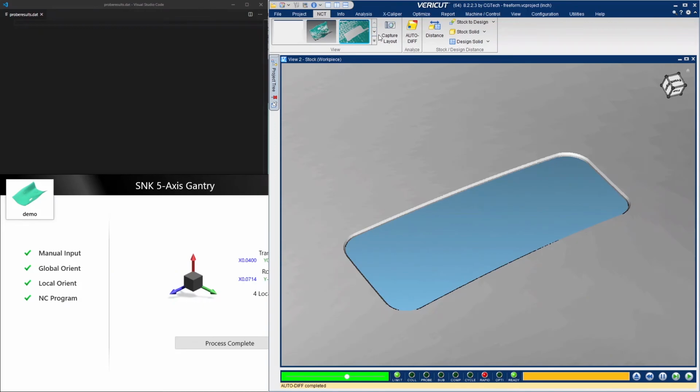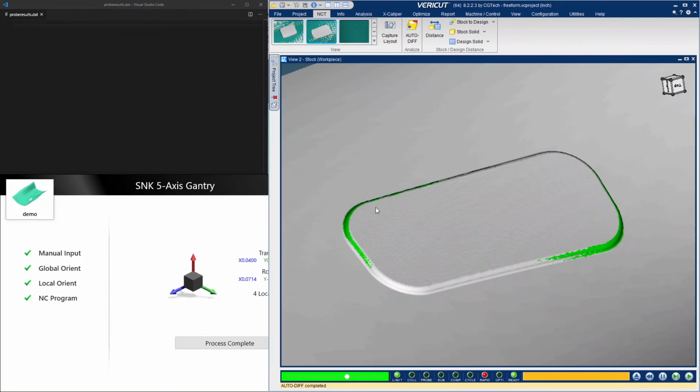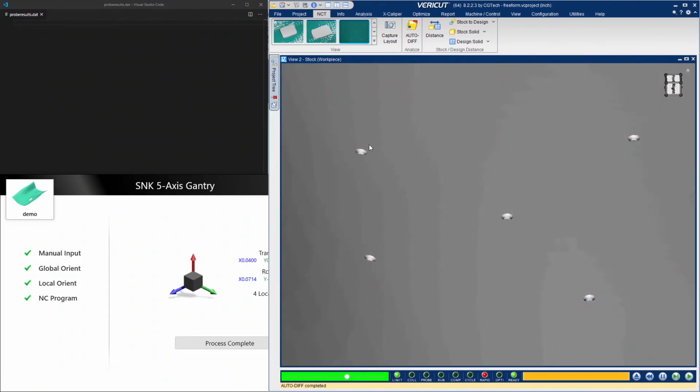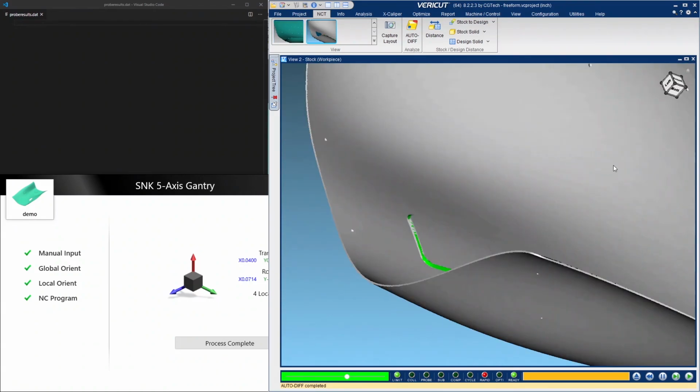We'll check our pad surfaces. And our pad surfaces, we can see the top surface of the pad is perfect. The contour around the outside, the blending is off just a little bit, just a hair, because of the way that we set up our operation in NX. But we can see that the correct transformation was applied to it because the top surface of that pad is spot on. Then we can see our countersink depths are drilled to the correct depth. And we can see that on the periphery of the part, there is no excess and no gouging on any side of this part.